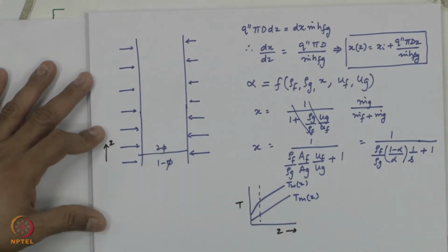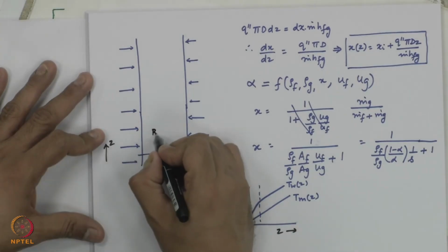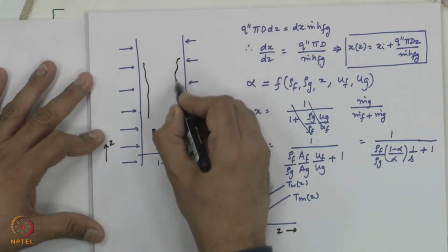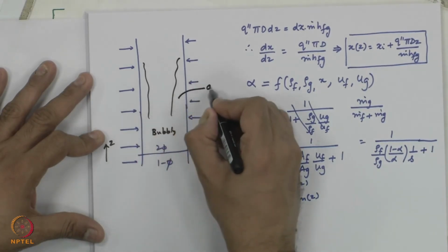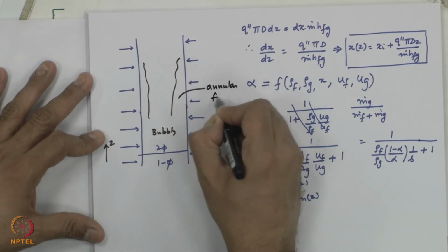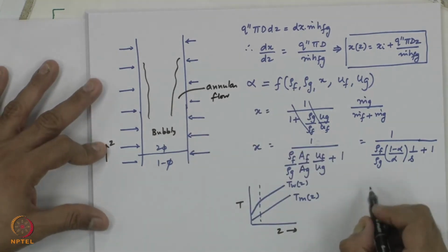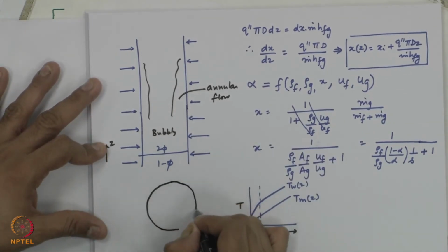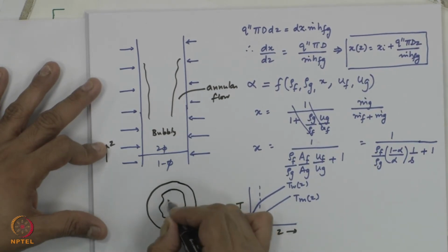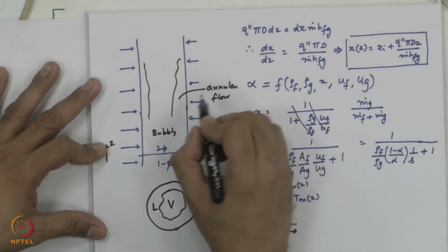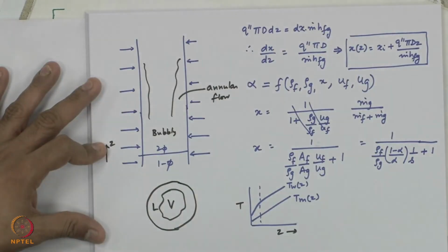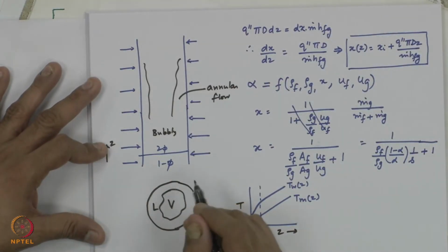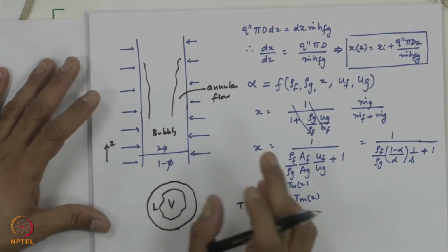Okay. Now, when you are in the two phase part, you would be in what we call bubbly flow here, and so on and so forth, and very quickly the flow will go to what we call annular flow. Annular flow represents the situation where you have vapor in the core and liquid at the wall. This is unlike film boiling, where you had vapor in contact with the heated surface and liquid away from it. So, we are talking of good heat transfer.